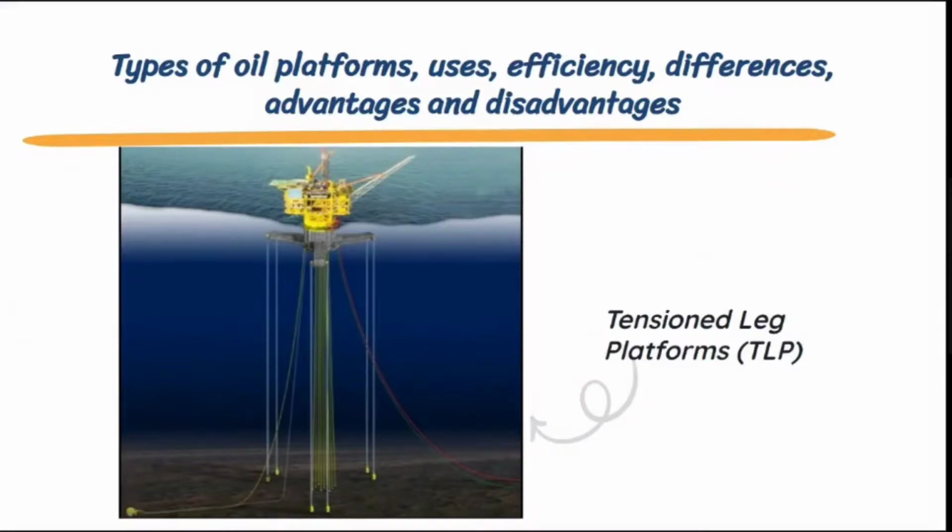The TLP is a system similar to the semi-submersible platform, except that it is anchored to the bottom by means of vertical elements, which are kept in tension due to excess flotation in the platform.